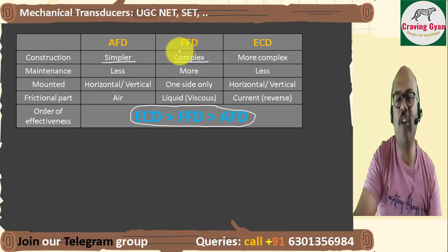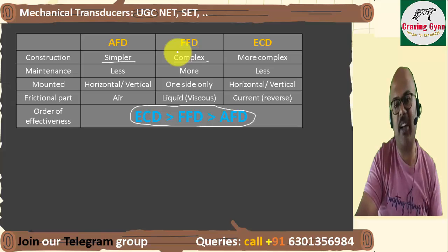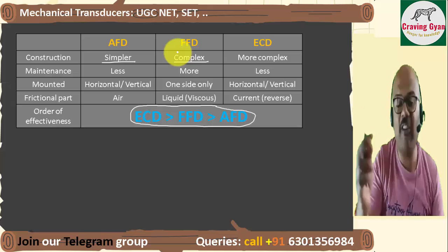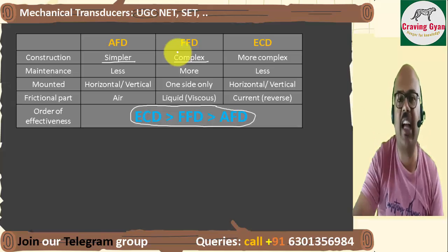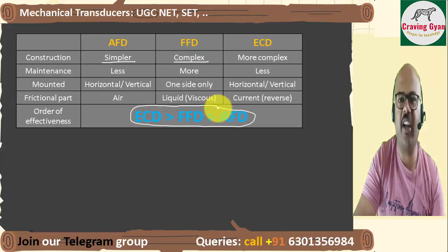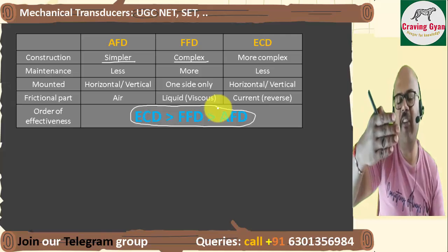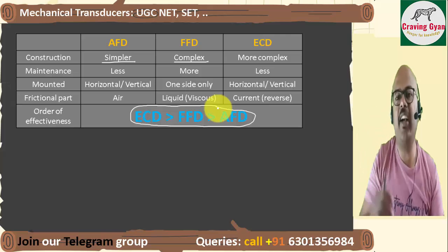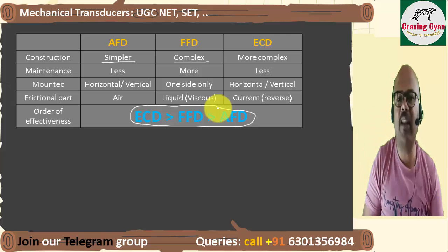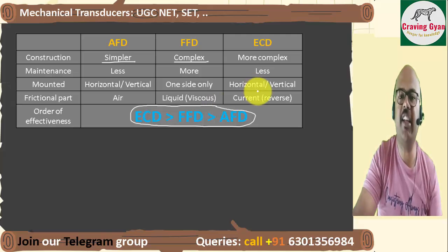In the case of fluid friction damping, suppose you have designed it for vertical mounting. Horizontally you can't place it. Why? The fluid may come out, or there will be a chance of leakage. Protecting the liquid is very important. One example: a bike will anyway be in the standing position. If you tilt it and keep it for 1 month, many things will get stuck. There will be an oil leakage, and a spillage in the piston rings and all.